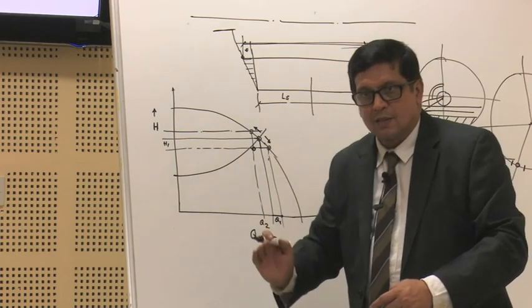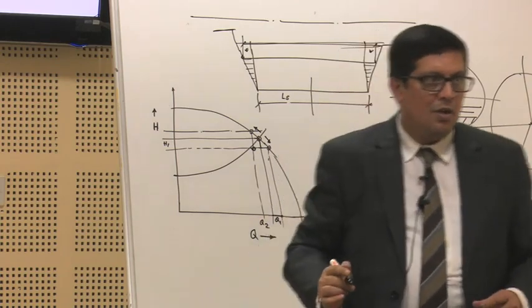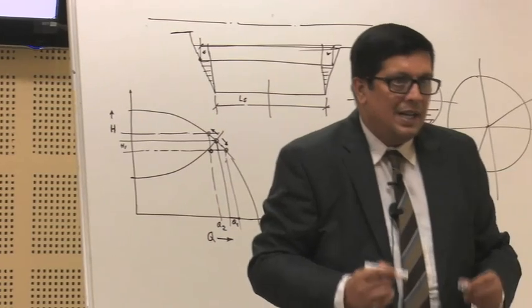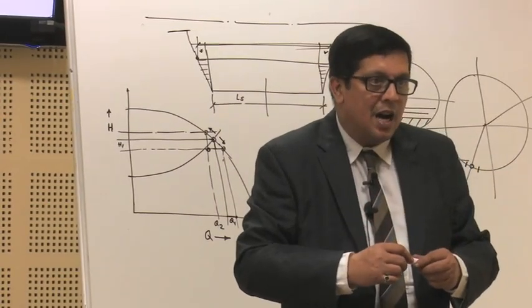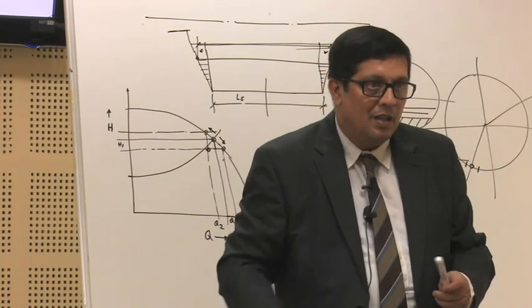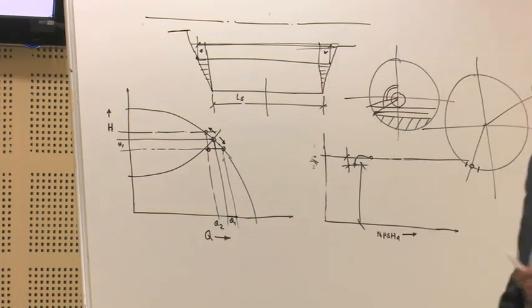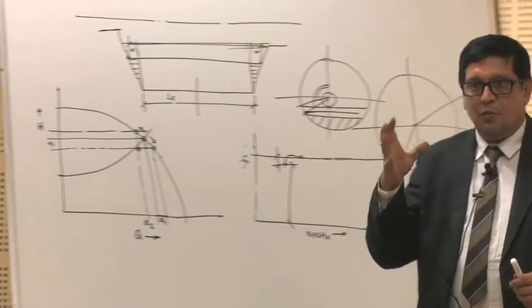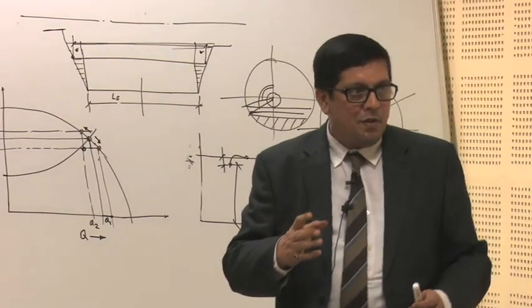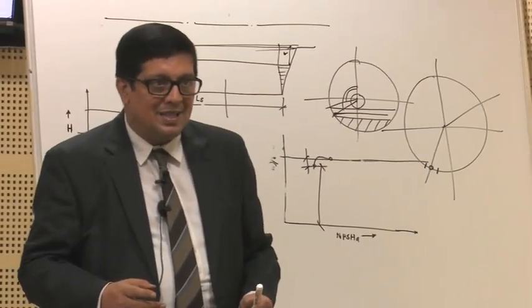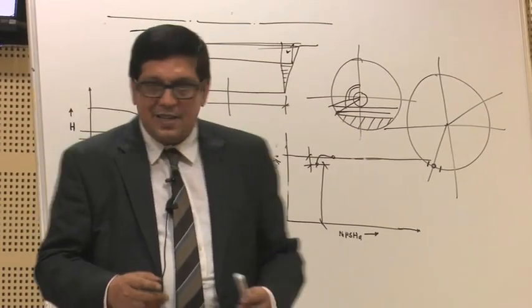It will do like this with the flow fluctuation, okay, which is known as the hunting of the pump. It is very common in the industry, hunting of the pump, right. So, if there is a hunting of the pump, what happens? The flow fluctuates, and the cyclone performance, if any cyclone is connected with that, gets affected. It is a very interesting thing.